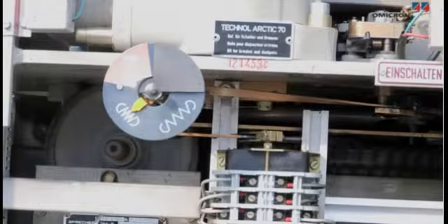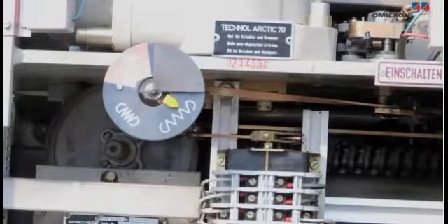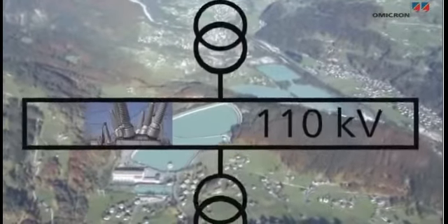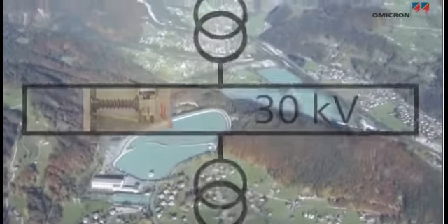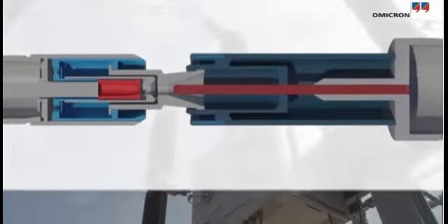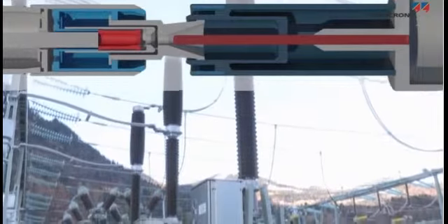Circuit breakers allow the flow of energy to be controlled by safely switching currents on and off at all voltage levels of the energy grid. In the open position, they have to ensure isolation across the switching distance, between phases, and to ground. In the closed position, they have to allow the energy to flow with minimum losses. They need to be able to reliably interrupt short-circuit currents without damaging themselves or adjacent equipment, even after long idling times.